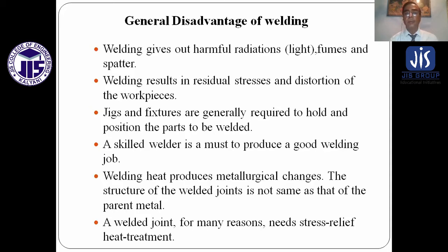General disadvantages of welding. Welding gives out harmful radiations, that is, X-rays, light, ultraviolet rays, fumes, and spatters. Welding results in residual stresses and distortion of workpieces due to heat. Jigs and fixtures are generally required to hold and position the parts to be welded.